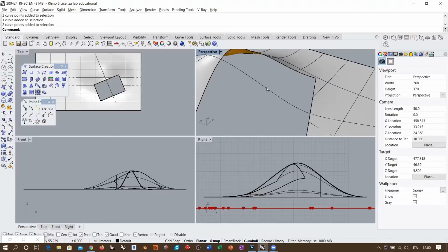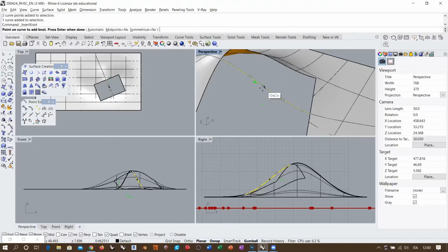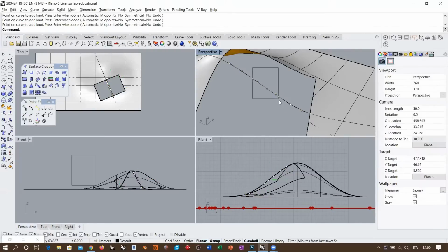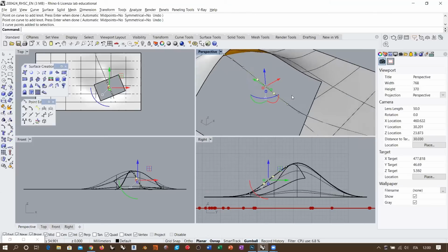And if I want, I also can add other knots, for example, 1 here, 1 here, and 1 here, okay? Other 3 knots, which means other 3 control points. So you have 3 for initial curvature, 3 for final curvature, and 3 that make this curve a degree 3 curve. These points obey the rules that we saw for degree 3 curves in terms of topological editing.